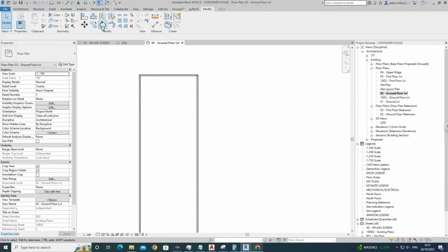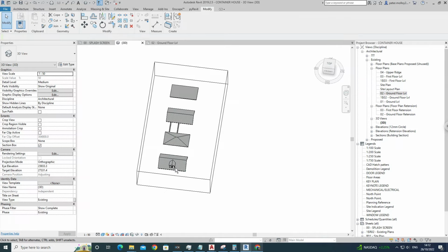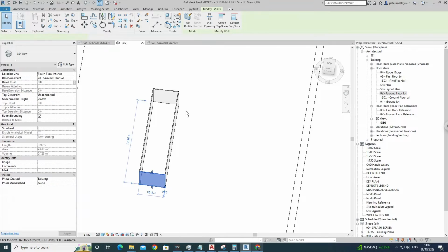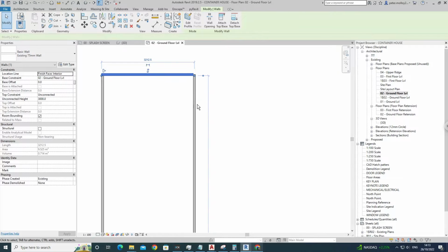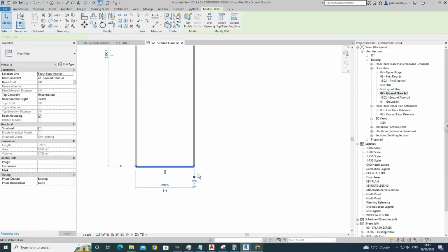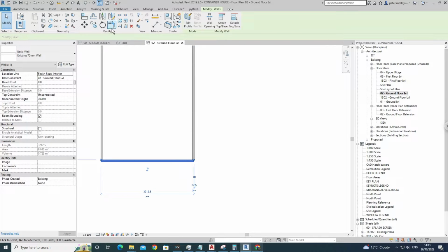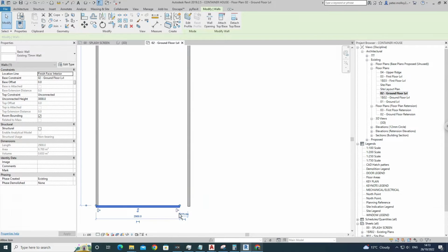Oh, these aren't connected. I'll just connect this fella here. Why aren't you connected? These are probably coming in at different extents. I just removed these roofs from a previous project. Yeah, so I've disallowed the joints on these walls. That's why they're not connecting properly. So now once I press these, as you can see, once this little fella comes up here, that means it won't connect to the wall adjacent to it. So I'll just click these off.